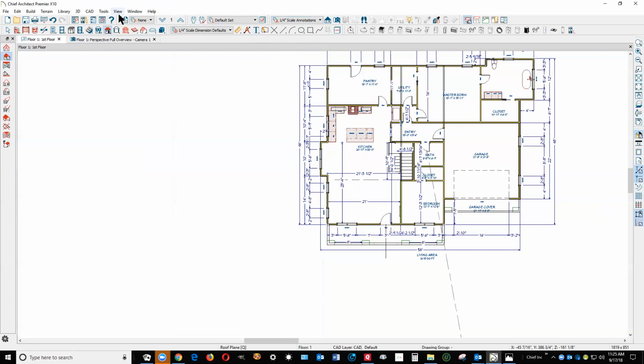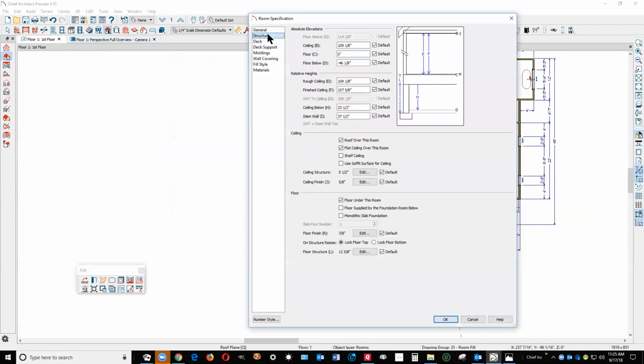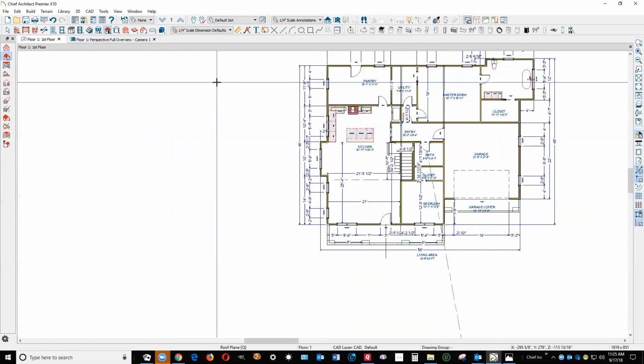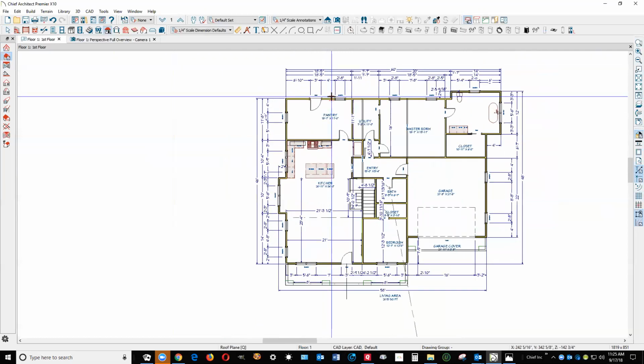And it looks like the ceilings are 9 feet. Let's see what you've got them set to. Okay, that's out of the box default, which is 9 feet. So I'm going to assume that that's correct. It needs to be correct if you want to not waste a bunch of time building it wrong.